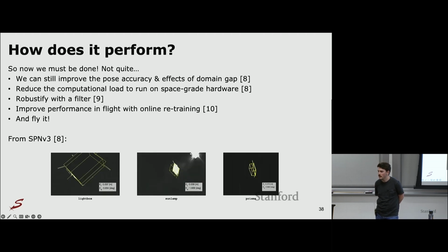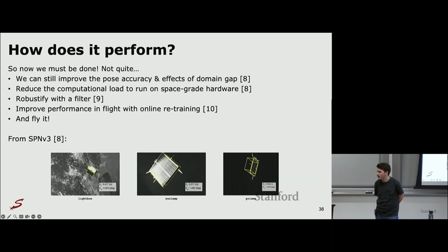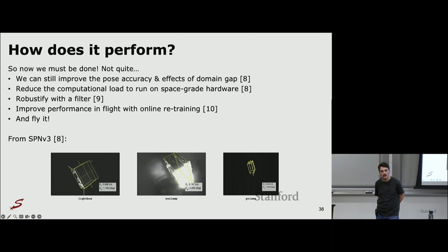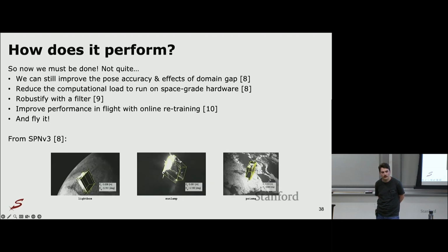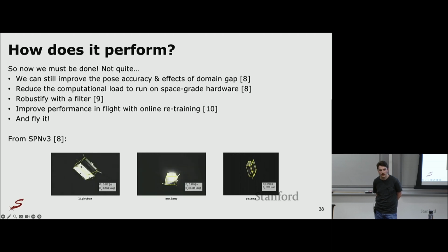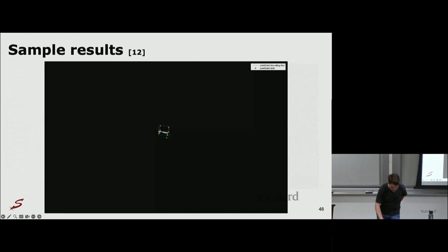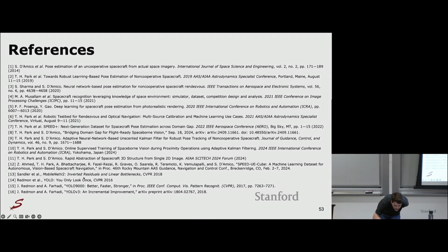Yeah, to some extent, that's what you're doing with temporal filtering, right? If you use some sort of EKF, say you get a bad measurement, you can still get a pose estimate because it's part of your EKF time update. Paul cited a paper where we do exactly that. The net generates those key points, which are used as measurements by an unscented Kalman filter. The unscented Kalman filter determines the pose over time using knowledge of the dynamics, which is equivalent to what you are saying about video.